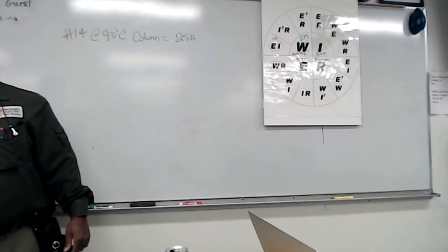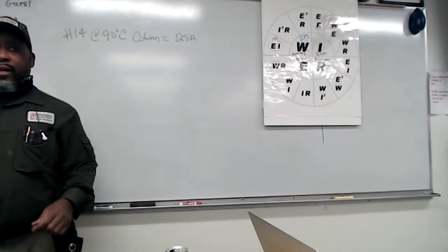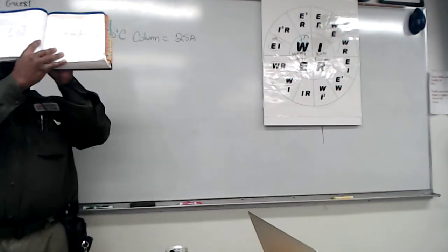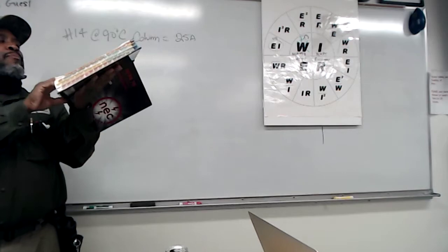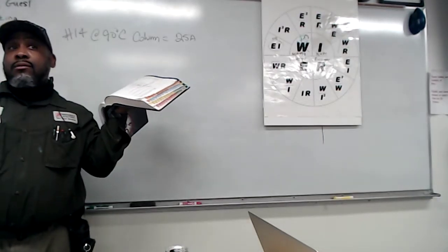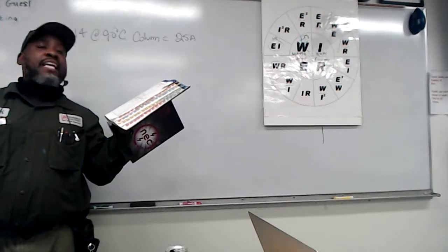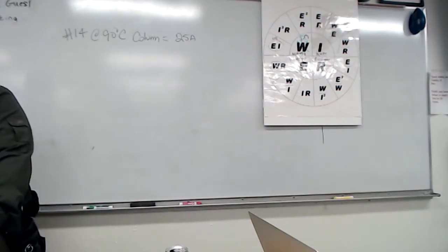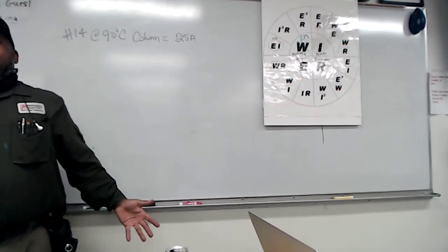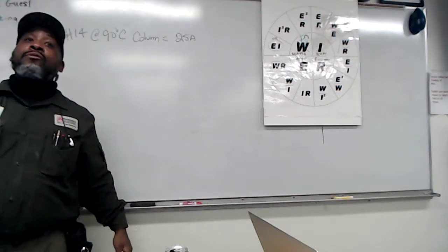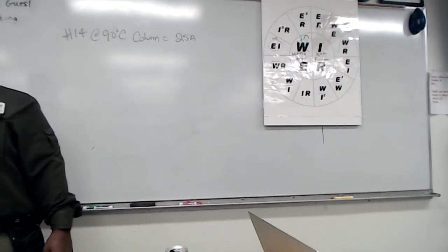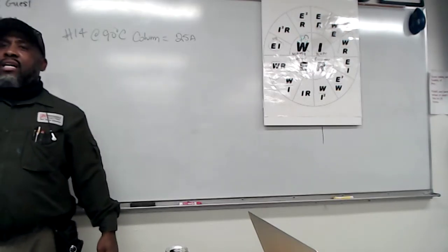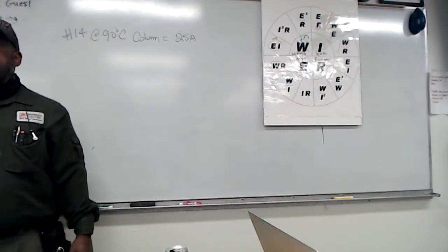table 310.15(B)(1). Look at my code book. I got that boy highlighted. You know why? Because what's going to happen, you're going to make a mistake and use 310.15(B)(2), and table 310.15(B)(2) ain't going to work. So if I was you, I'd highlight that, circle it, put an X over it, do something to let you know this is the only table I'm using for correction factors when it comes to temperature. Got that? That's on the journeyman exams, math exams. That's the only table I'm using. Got it?